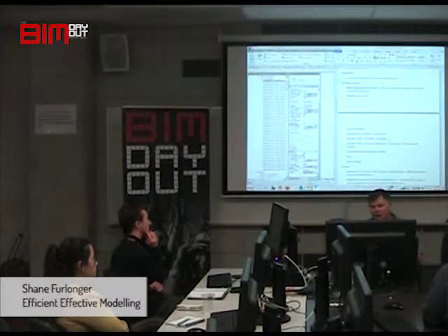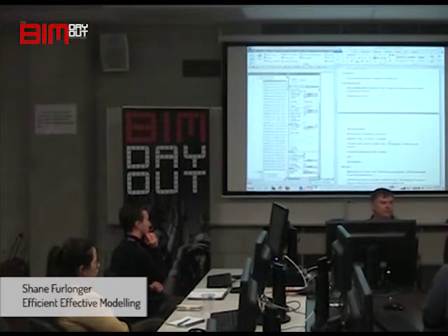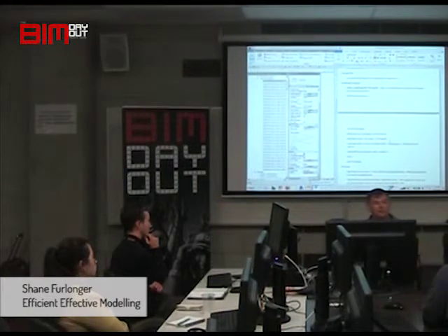So the legend phase, really useful for setting up an area where you can have a play with stuff and not have it affect any of your schedules. Also great for doing a window schedule, door schedule, or a wall schedule, or anything else like that, or wall legend, because you can tag it, you can dimension it, you can do all sorts of things to it that you can't do in a regular Revit legend. Yeah?